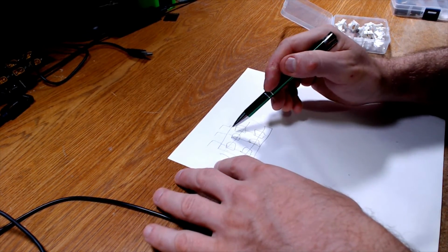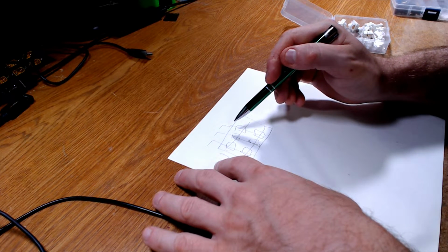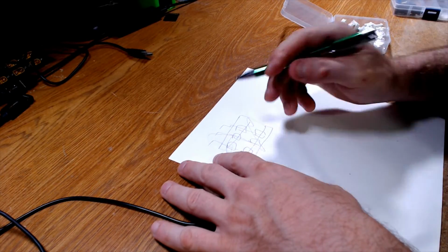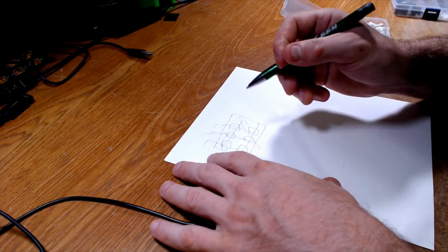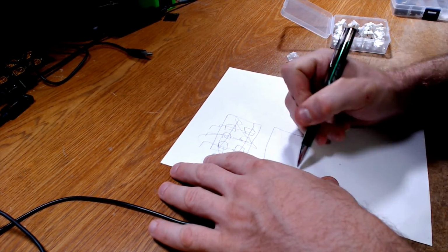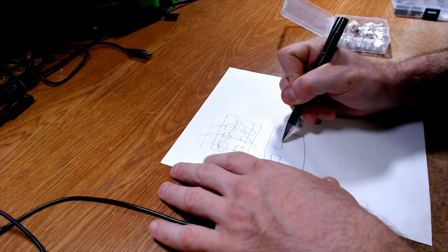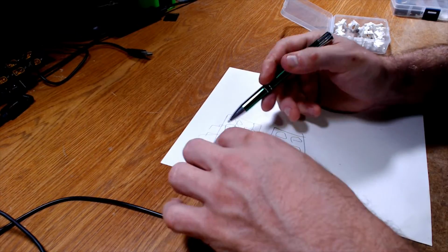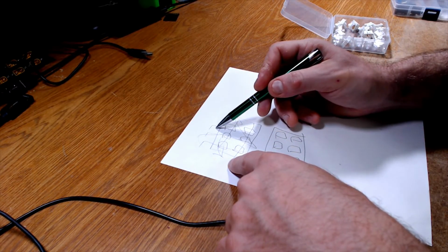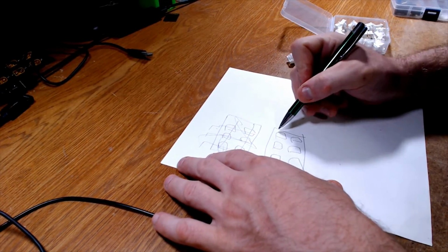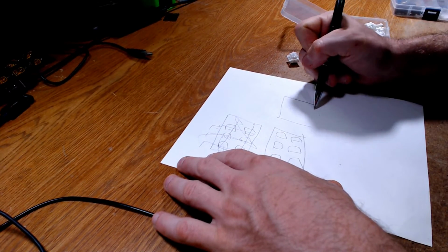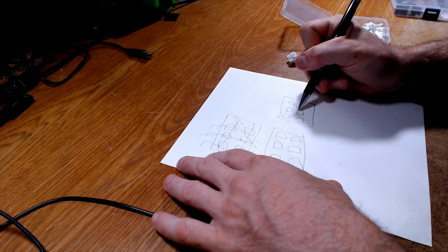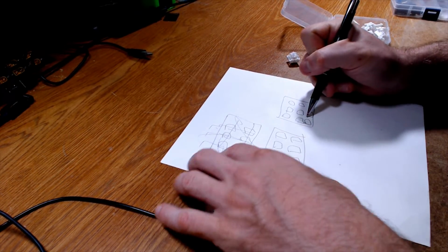Or no, actually, derp. That is not how that works, right? Anyway, we're going to multiplex the buttons. If I could edit that part out, I would. My brain is just totally derping at the moment, but we will multiplex these buttons so that we do not have as many wires. We do not have 6 wires. Oh, that's 5 wires. Yeah, hold on. Maybe I'm not derping. Maybe it's just a bad example. Let's go 3x3 really quick. Yeah, 3x3 would be 6 wires, and that gets us 9 buttons. Okay, yeah. So I scribbled that out.